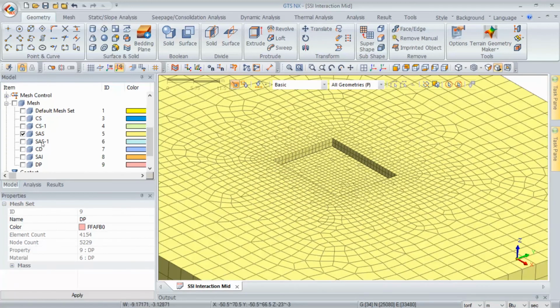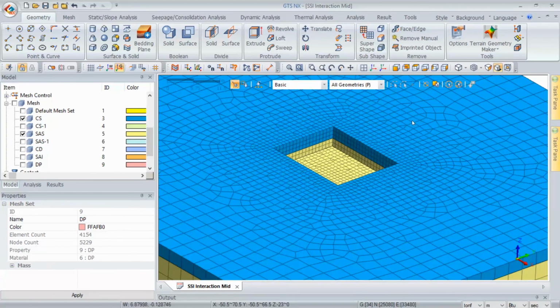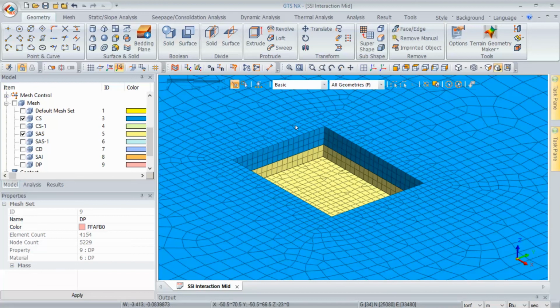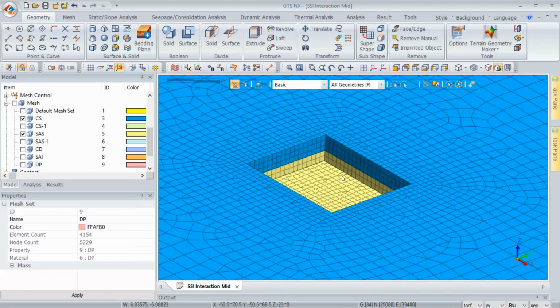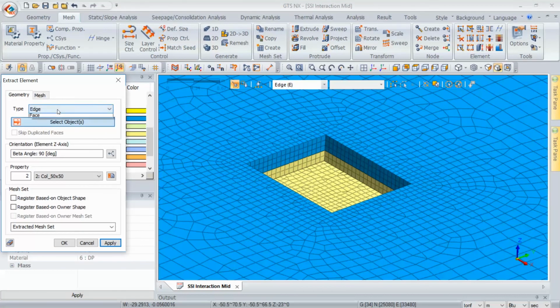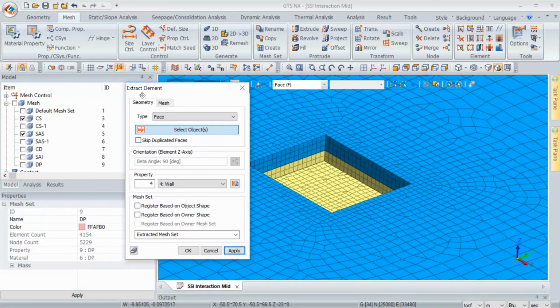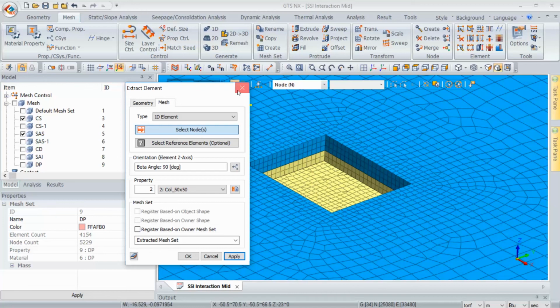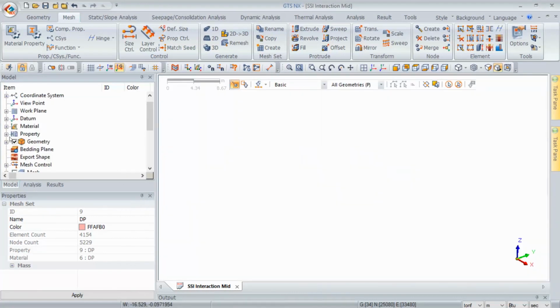And what we're going to want to do is actually both of these. We're going to want to extract the wall elements and the raft elements from our existing soils. So first you model the 3D terrain, and then you get into the structural components in the case of the foundation. So for that, as I mentioned, we would use that extract command. We can either directly select from the meshes. That's a little tricky to capture all the elements, so it's easier to just activate the solids.